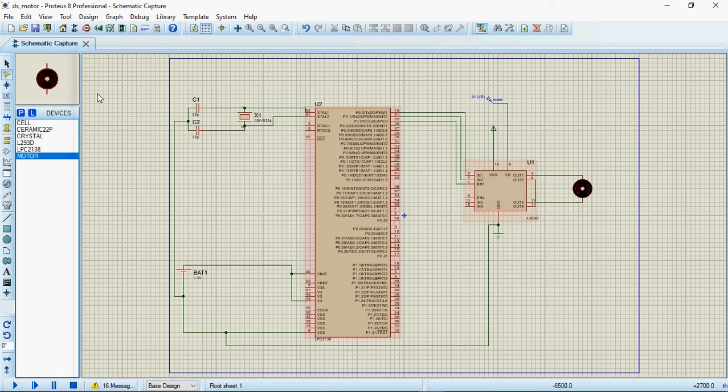Then the next component which we will pick happens to be the supply voltage, which you need to give to the motor. So you have two supplies to be given to this IC L293D. One is the IC voltage or chip voltage, which is 5 volt, which has to be given to pin number 16, and pin number 8 motor DC motor voltage you have to supply. So it is given with the help of this generator mode, and in that pick DC. Okay, and change this mode to